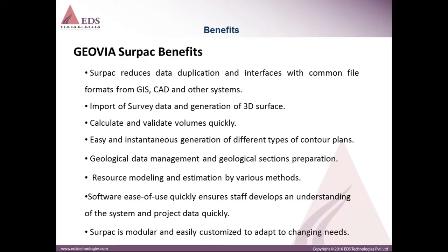So Surpac reduces data duplication and interfaces with common file formats, like with geoscience applications. So in college you will maybe have GIS or MapInfo. So you can use those data in Surpac and then work on that. And then you can import your survey data and generate a 3D surface. Once you have surveyed your entire topography or entire mine, we can import that survey data and create a 3D surface to calculate the volumes or to generate the contours.